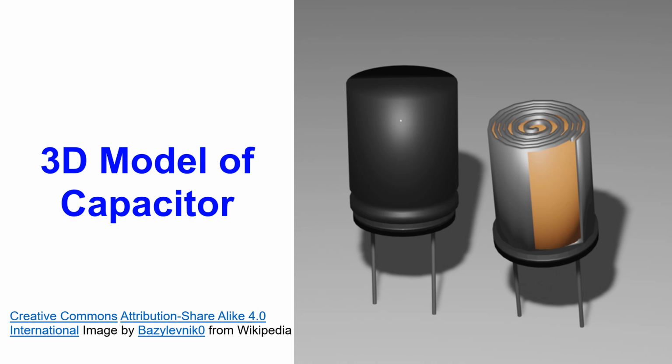Electrolyte leakage from poor quality capacitors could damage the printed circuit board as well. There could be self-degradation if left unused for a long period, like a year, and might lead to short circuit when full power is applied.